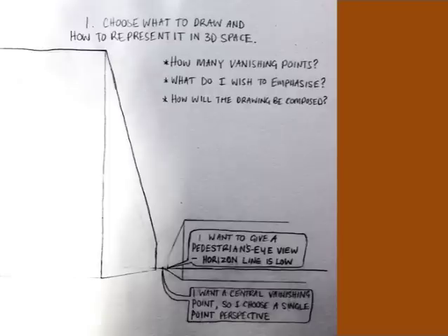Because I want to show the whole north face of the GPO facing into this very narrow lane, I want a vanishing point which is going to be visible within that lane. So that vanishing point will end just beyond the end of the lane. Because the vanishing point will be central, I have to use a one-point perspective. If I don't, I'll get all kinds of distortion.